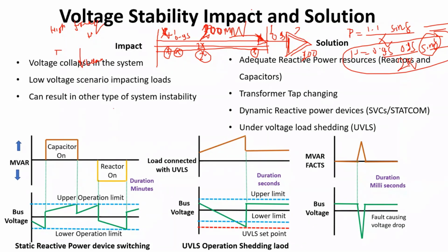So in those situations, what you will do is put under voltage relays over all these loads. Loads will not be one; it will be like one substation here, one substation here, one substation that is being fed from this main substation, right? So in case of any tripping, I have to bring this 200 megawatt immediately to 100 megawatt so that my voltage is within 0.95. So I will check what voltage drop I am going to absorb with n-1. Let us say it is 1 per unit, going to 0.8.